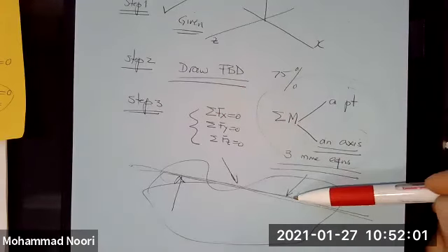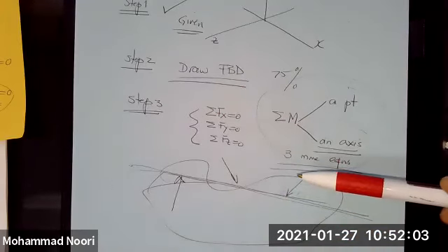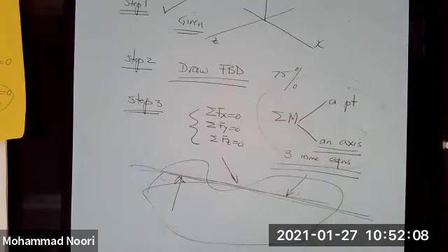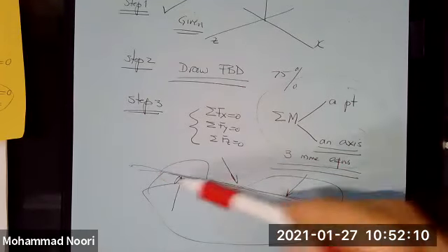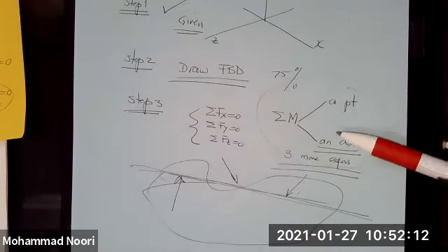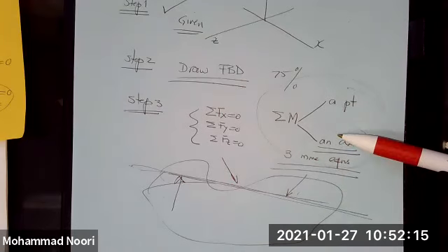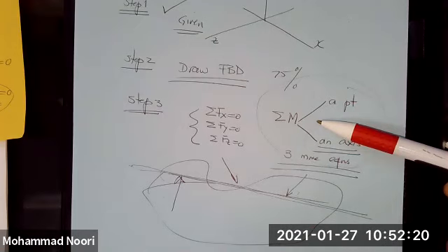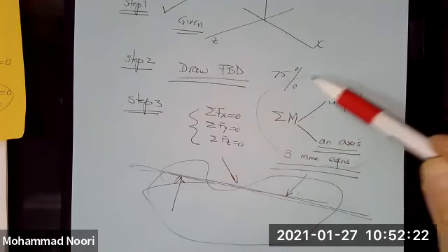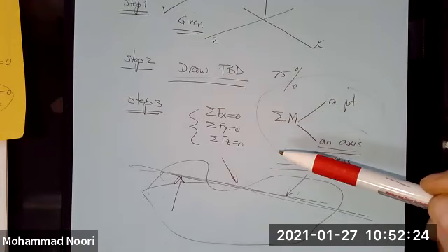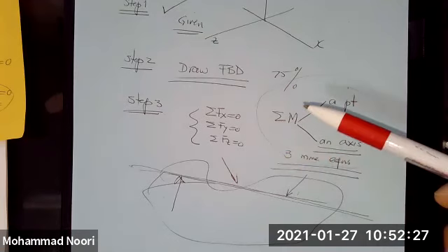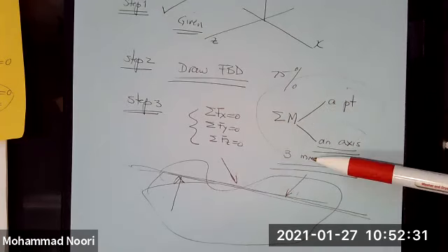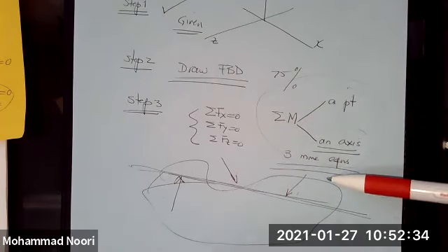In 3D, if you find an axis that intersects with as many unknowns as possible, you start with that equation, you may end up with only one equation, one unknown, like 2D. But you don't have to. You can just use the approach by taking summation of moments of all those unknown forces about a point, but you end up with 3 equations, 3 unknowns instead of 1 equation, 1 unknown first.